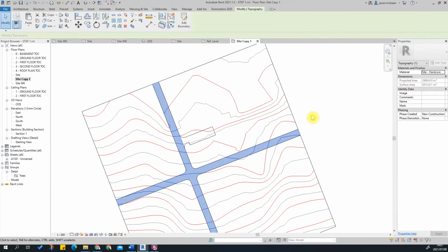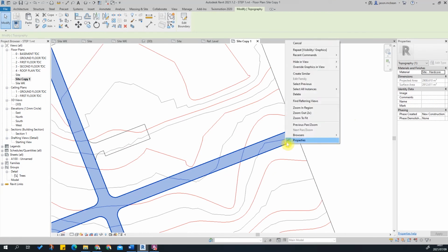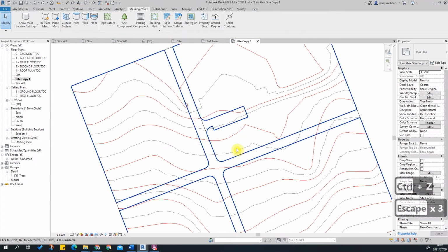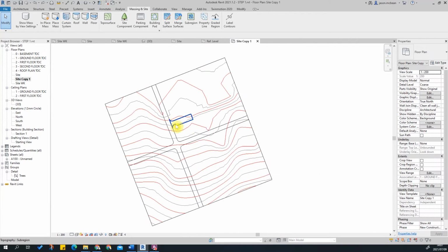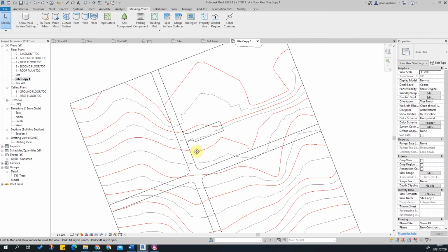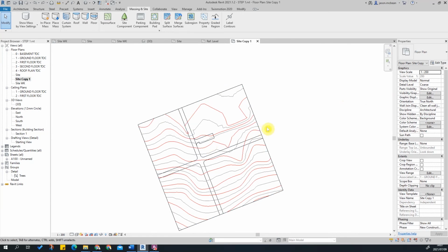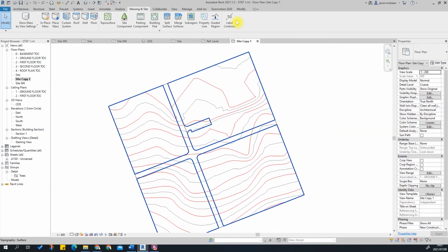Okay, so in AutoCAD, you've actually got to go and switch off these sub-regions. Let me just see if it'll hide and view elements. No, see, it deletes the, so it's part of the site information. Okay, now, unfortunately, there's no other way to do this. So what I typically do is I export this as a DWG file now, and I reload it in, and then explode it and get rid of the information I don't need. Okay, so I steal the contour information, maybe add some labels.